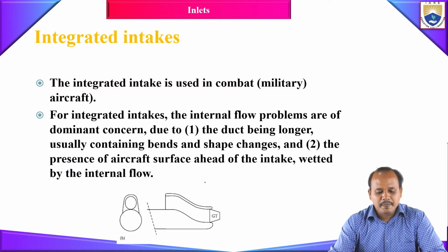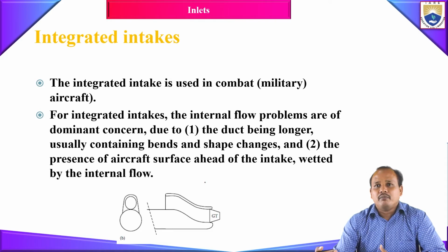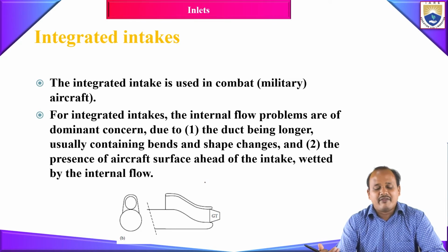And the next one is the integrated intake. So what is this integrated intake? Here the body of your aircraft and the portion of your intake will be integrated together, or you can say the part of your aircraft itself will act as an intake. For example, you see your fighter aircraft, you won't be able to see the engines outside, right? Have you seen any supersonic fighter aircraft where you have the engine outside?